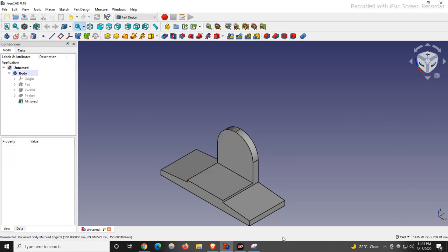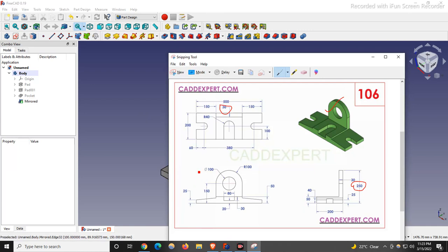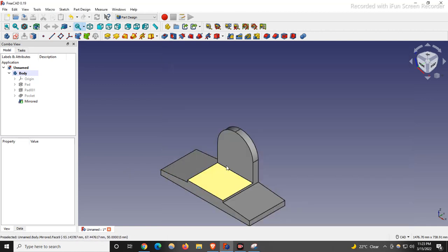If instead of this 100 mm diameter hole, there is a 10 mm blind hole, we will go with the hole feature, but it will actually be manufactured with milling operations. So we will make this feature as a cut.